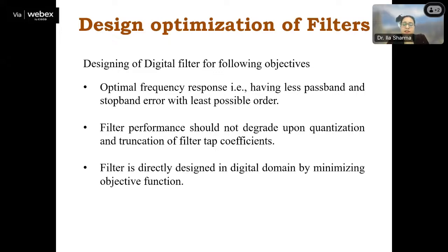As you increase the order, complexity also increases because it is directly connected to the increasing number of adders and multipliers. But as you increase the order, you get responses more accurately, nearer to the ideal one. In many techniques, it has been observed that the higher the order, the higher the performance, but also the higher the complexity.